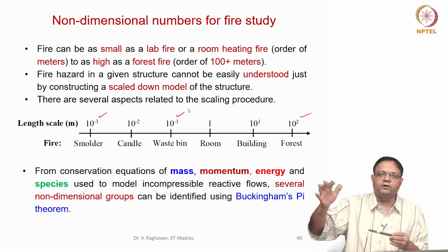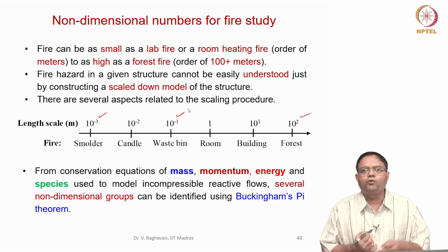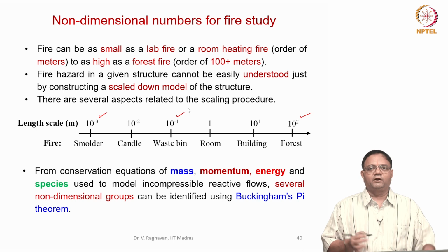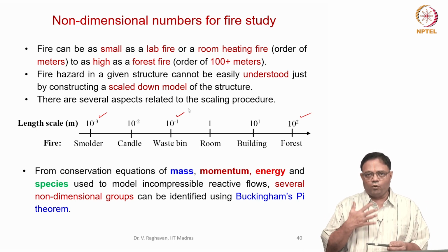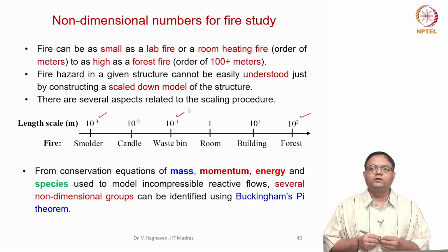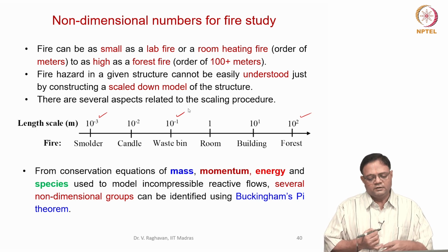Then after 25 centimeter, it will become fully turbulent. Similarly in a flow, initially the flow can be laminar at low velocities for a given duct or any pipe. Then as the flow velocity increases, there is a transition, because the Reynolds number has a critical value at which this transition occurs.